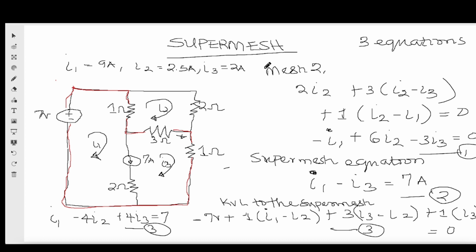If the circuit is non-planar, then there is no choice. We have to use the supernode, provided that we are indeed considering the analysis of a planar circuit. However, there are situations in which one technique has a small advantage over the other. If we plan to use node analysis, then a circuit with n nodes will need n-1 KCL equations. That is, if we have 6 nodes, we're looking for 5 KCL equations. Each supernode defined will further reduce this number by 1.